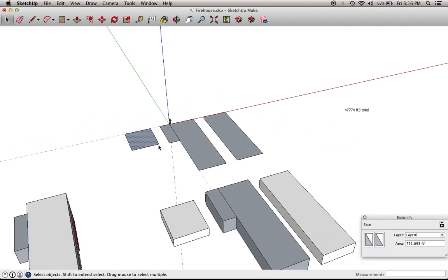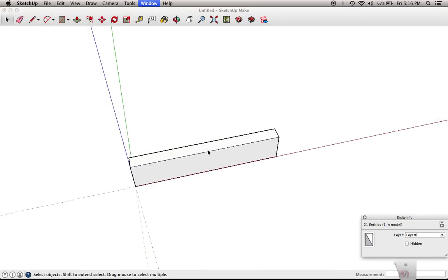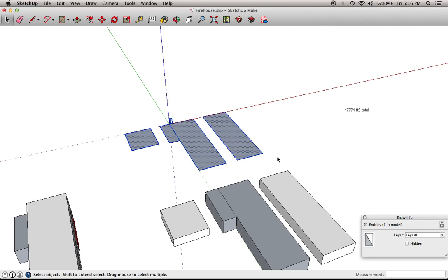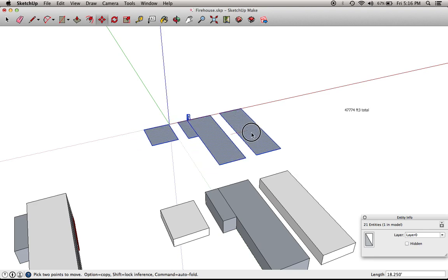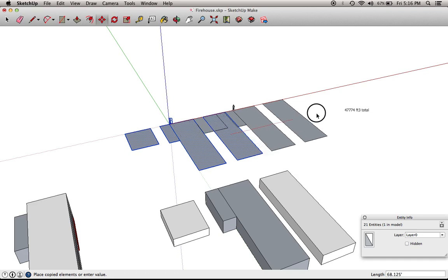And not only that, but I then take these three things, copy them, and I go to Command M, and that's... oh my goodness, that's not what I meant to do, excuse me, just M. M is move. So if I grab this thing, and while I'm moving it, I hit Alt, that will make a copy of it automatically.